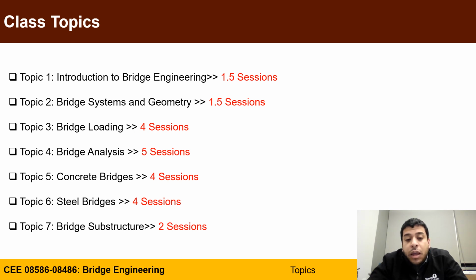And topic 5 will cover principles of designing concrete bridges from different aspects, from bridge decks to pre-stressed concrete girders to barriers, etc. Topic 6, steel bridges, will deal with design of steel bridges, mainly composite steel I-girders or built-up sections, and also design of bracing, horizontal bracing and cross bracing in a steel girder.